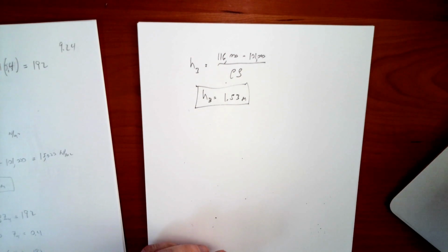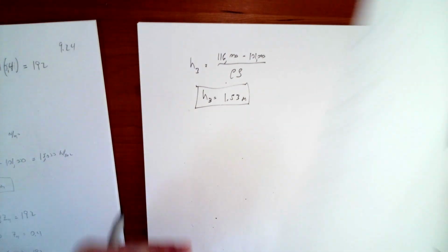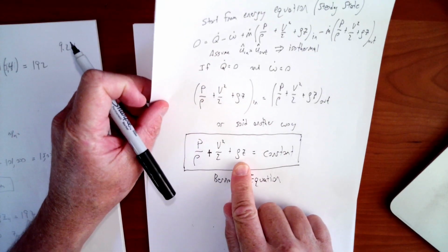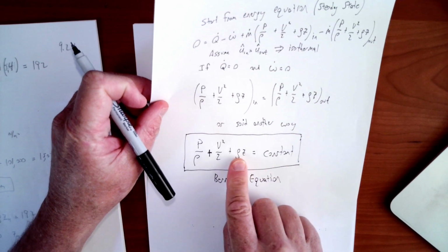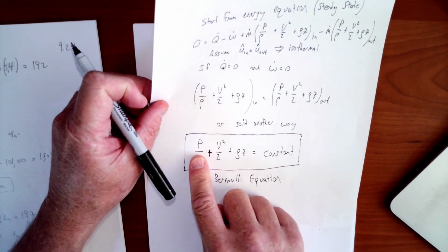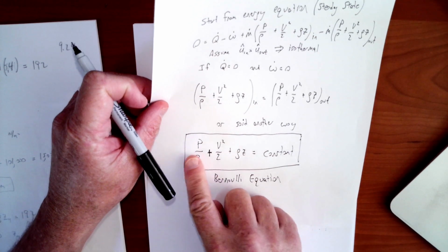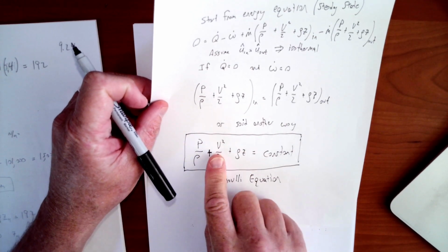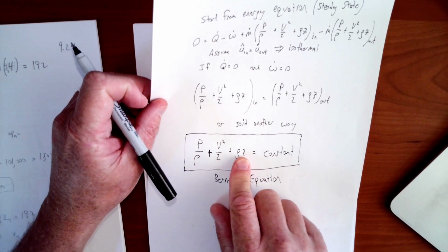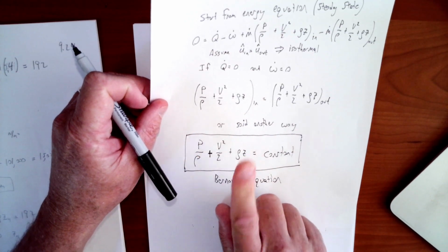And according to the Bernoulli equation, that's going to add to this. So if this is going to all equal a constant, a higher elevation is going to have to mean a lower pressure or a lower velocity. Well, velocity stayed the same, has to because of conservation of mass. So therefore, the pressure must have dropped because the elevation is higher.